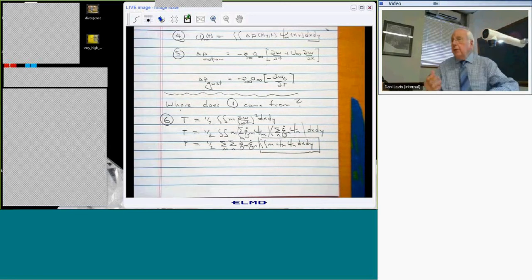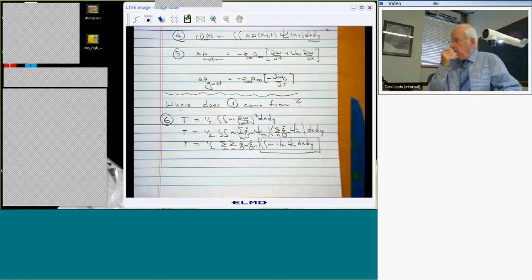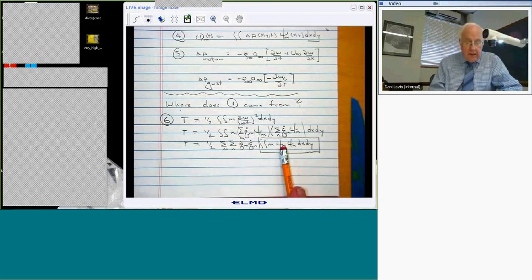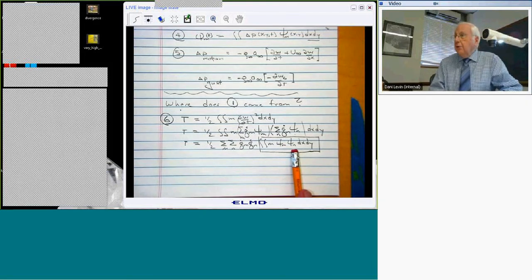But now here's where the Eigen Modes come into play, and that's why we almost always use Eigen Modes for flutter analysis and aeroelastic analysis. It'd be nice to use orthogonality. And the Eigen Modes are orthogonal. They're not the only modes that are orthogonal in the world, but the Eigen Modes are always guaranteed to be orthogonal. That is, this integral is 0 unless these two indices are the same.